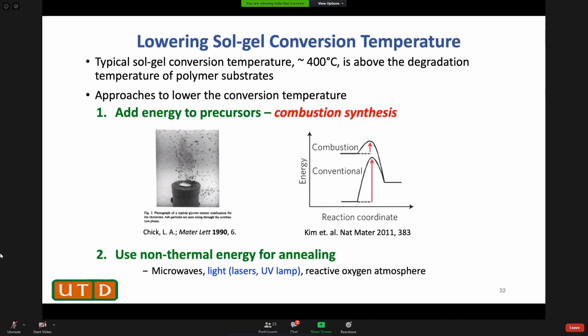We haven't tried zinc oxide. One reason we would like to stay with amorphous oxide is if you are on a plastic substrate and you bend it, crystalline oxide is not good, right? They're going to crack along the grain boundary. I wouldn't have thought zirconia would stay amorphous, but it does. Or maybe they are nanocrystalline.